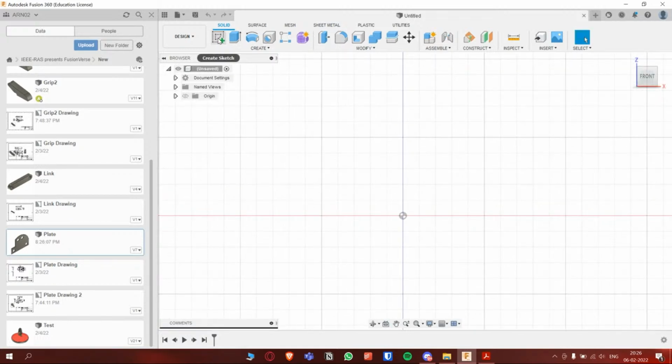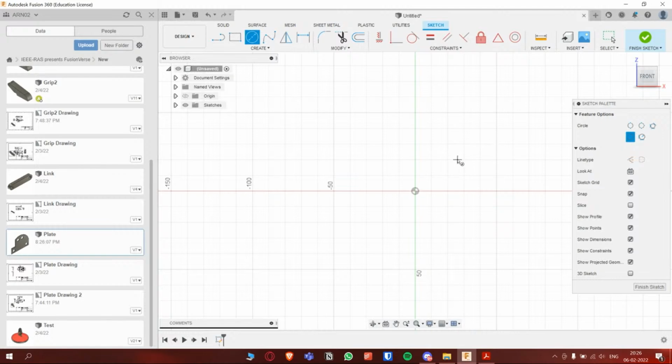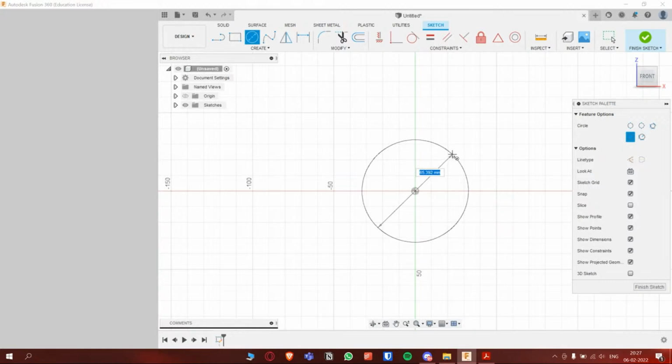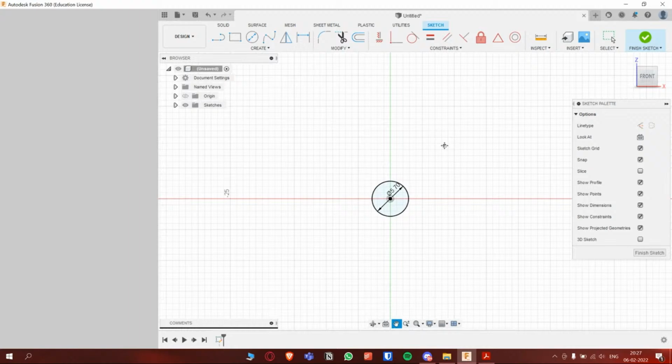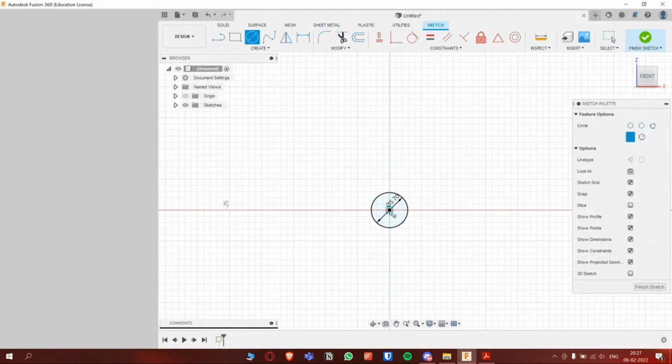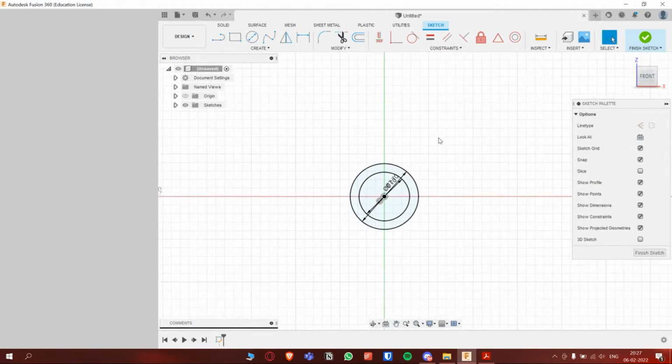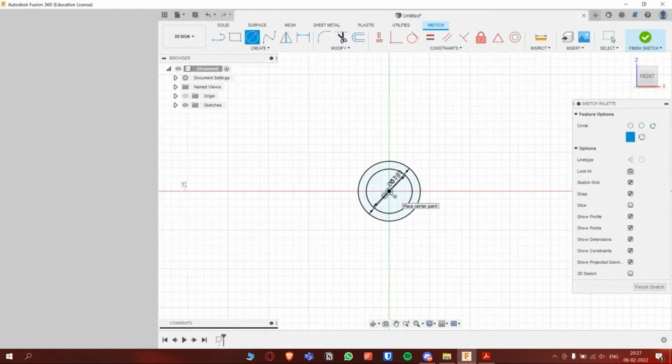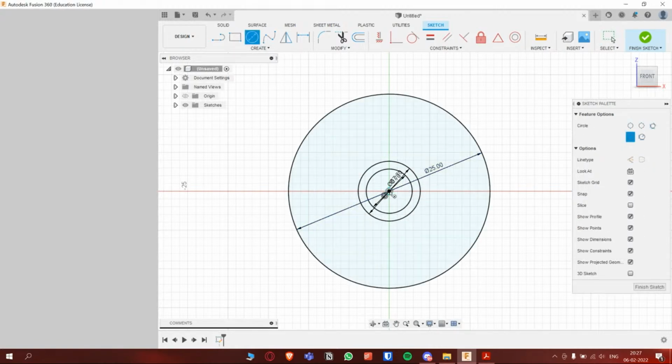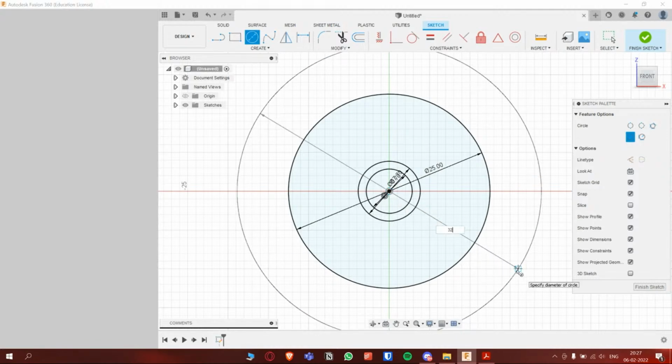All right. Click on Create Sketch and click on C on your keyboard. We just clicked on the front view. So click on the origin and give this as 5.7 millimeters diameter. Let's zoom in. Again, click on C on your keyboard. 7.7 millimeters. Zoom in again a little bit. And another one, 25 millimeters in diameter. And the last circle, which is 32 millimeters.